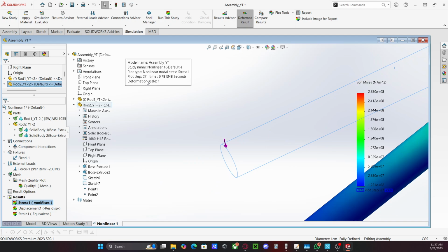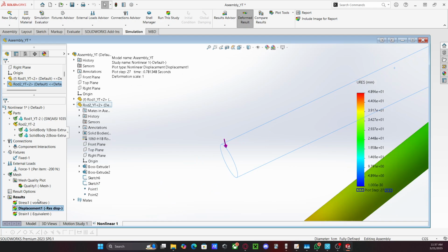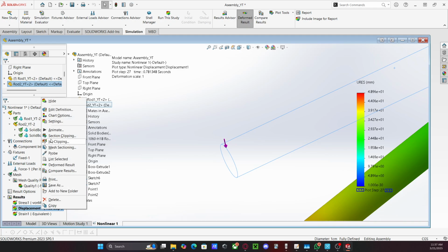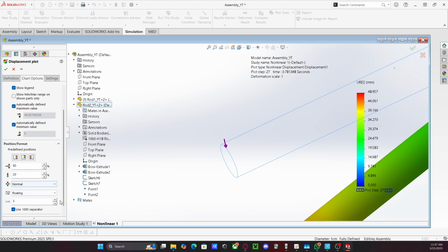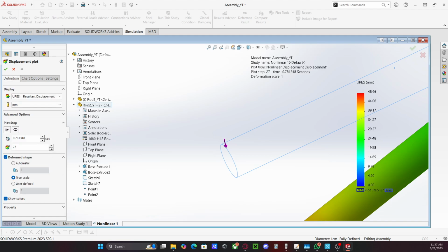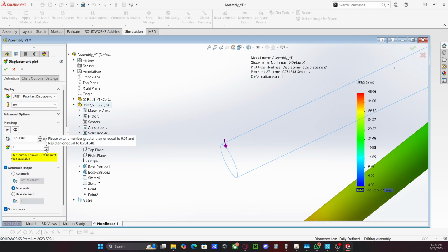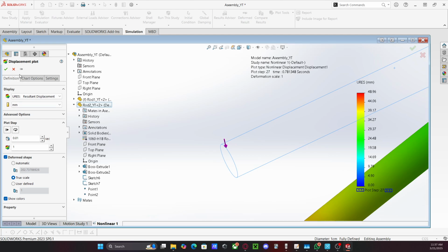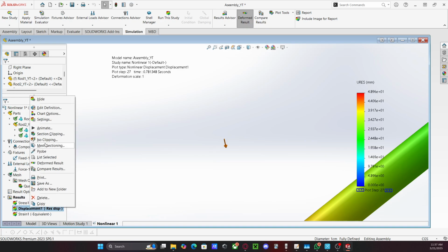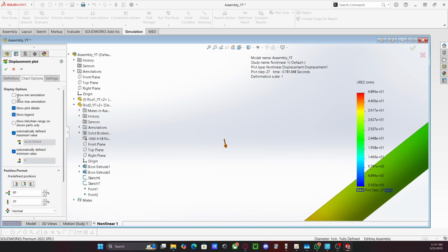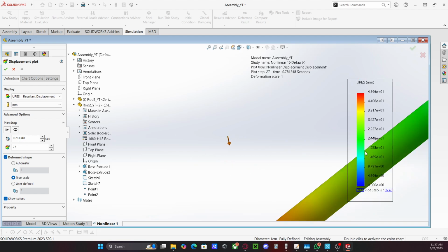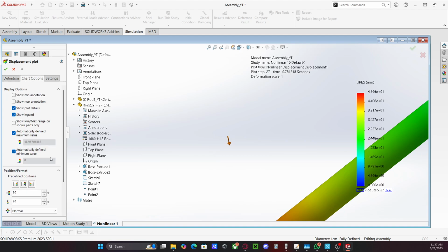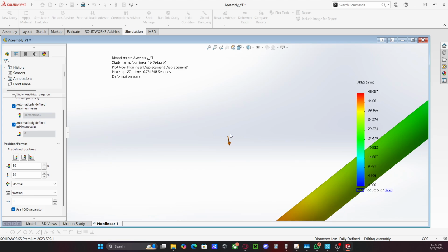So at this particular step, the displacement was around... if we look at our chart options, go down, scientific floating, let's see this definition. So we can't go any higher than this. Maybe if I go back, displacement, chart options, I can't increase this step size. I can't increase the step time to 1, which we should have, but we don't at the moment. So chart options, scientific floating, press OK.